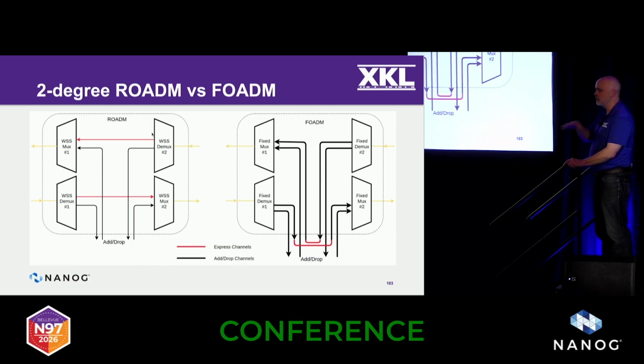The complexity will increase as you have more and more sites, and therefore you might need to consider doing something that can either equalize the channels or use WSSs and equalize them with that. Because you can equalize channels with something besides a WSS, but it's another device.